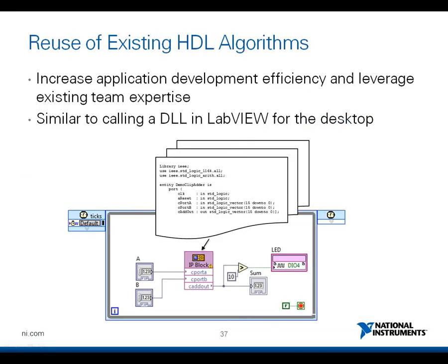In addition to IP that's written in LabVIEW, you can also reuse any HDL code. You may want to consider this if you have existing IP written in HDL, or if someone on your team is a specialist in HDL. You can import it into LabVIEW FPGA through the IP integration nodes, similar to calling a DLL in LabVIEW Real-Time or LabVIEW for the desktop.